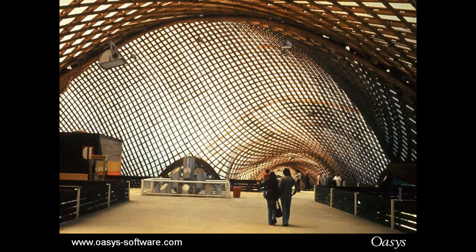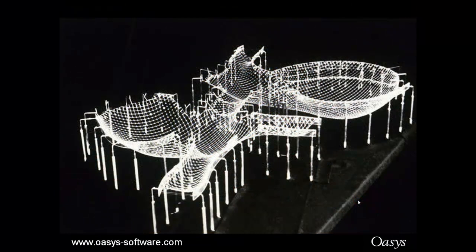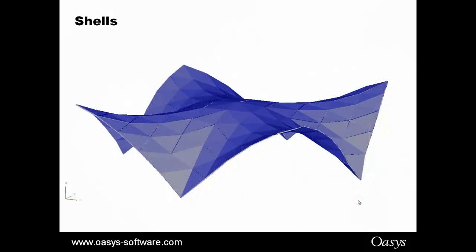Again, the geometry is crucial to the stiffness of these structures to minimise bendings and so on. Danger loads on these, things like snow loads, obviously asymmetric loads. This is again from the 1970s, 1975. Hanging chain models were used to create the geometries, and then very careful measurements to get the geometry. Today we'd use GSA for using either soap film method, using inflation pressures, or these normal pressures.